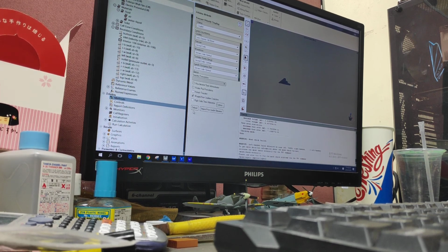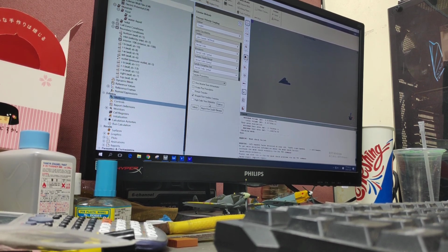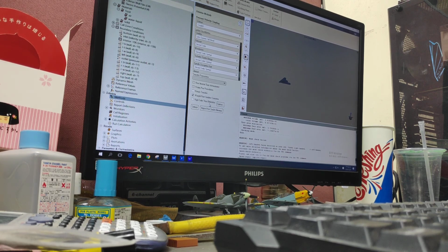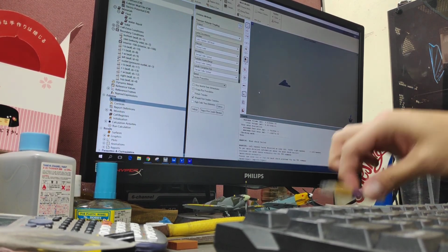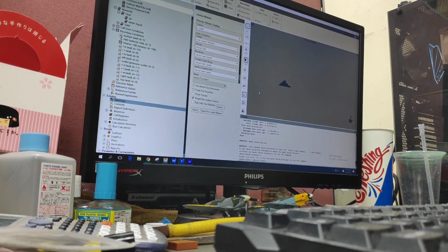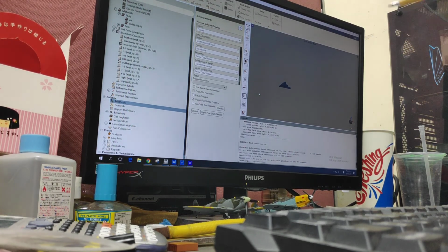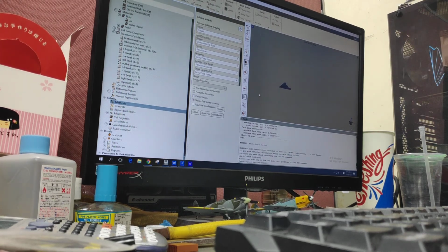And this one, high order term relaxation, only choose if your convergence is very hard. If it's very hard to converge, you choose that. But if it's not very hard to converge, skip it.